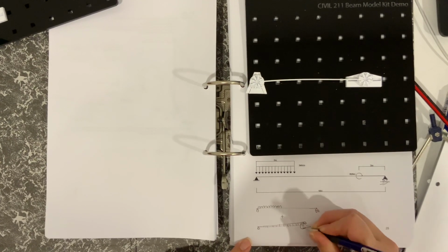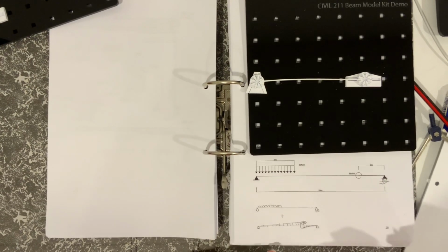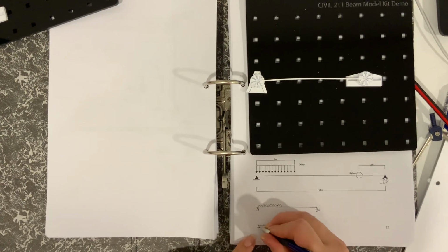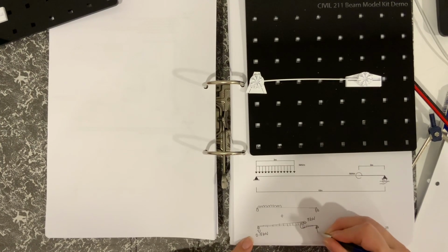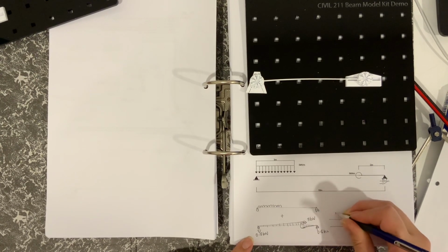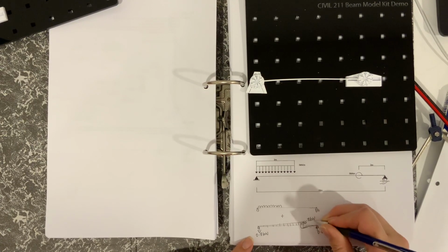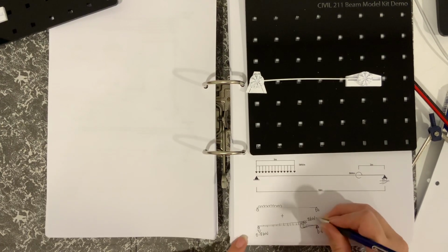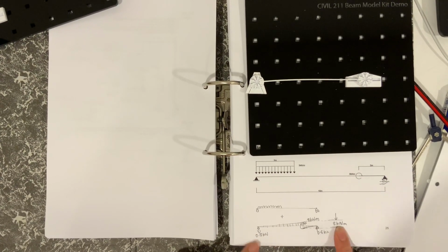So the precise values, of course, would depend on the reactions that you've calculated. So if you've applied the 8 kilonewtons here, you would probably find out that that reaction there is 0.8 kilonewtons, and you would probably find out that that reaction there is 0.8 kilonewtons. And when you plot the bending moment diagram, you would find that that distance there, from there to there, would be 8 kilonewton meters. So that would be the bending moment diagram.